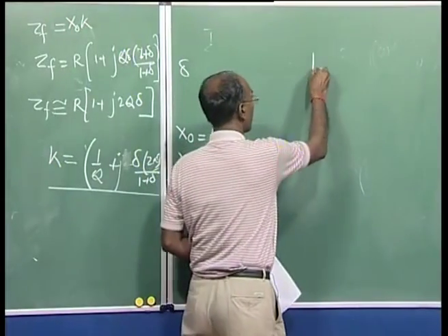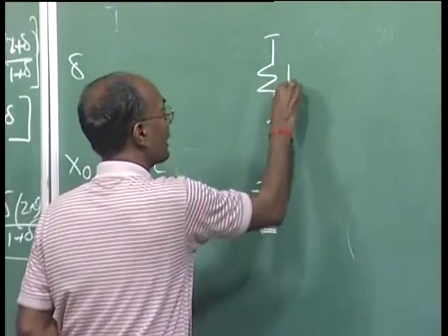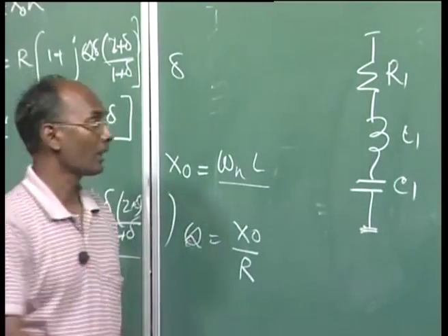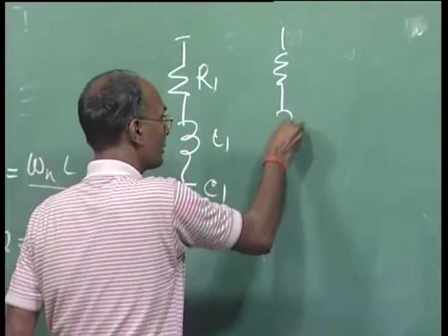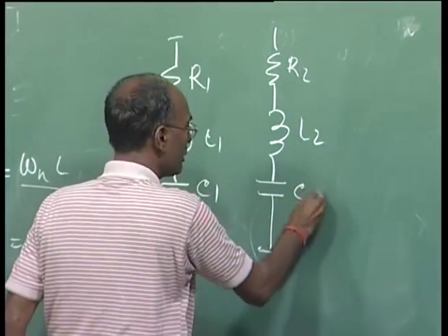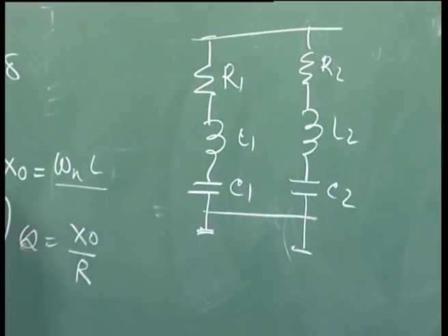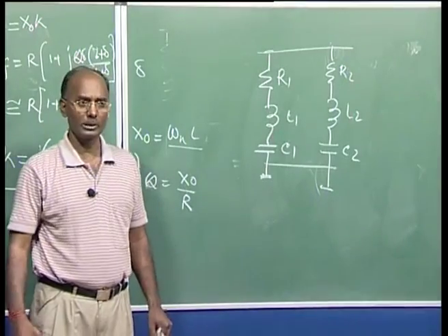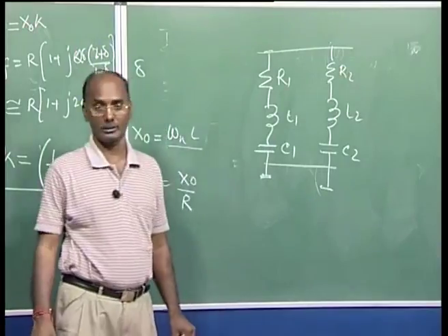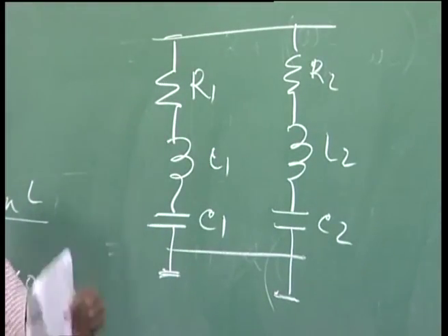Like here you have your resistance, here your inductance, and this is your capacitance, here the ground. I can say it is R1, L1 and C1. This is tuned for one frequency, and if you have another impedance here, resistance here, I can say R2, L2 and C2. If they are connected in parallel, then we can say it is a double tuned filter. There is no special thing here, but we have two big inductors together, and these inductors are really sustaining the total voltage of the supply.